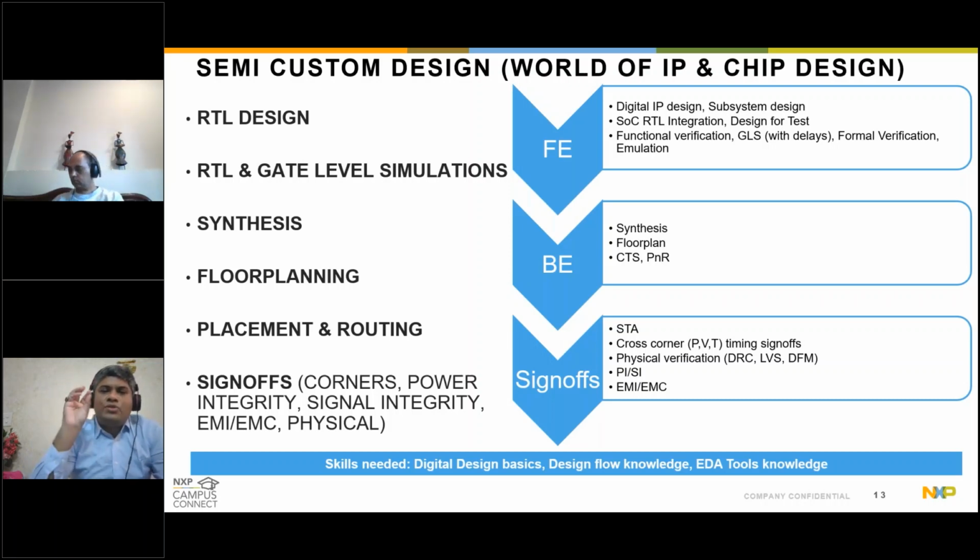But in this slide, we are talking about digital IPs, which means the reusable blocks or reusable design elements which get integrated into the larger chip. In the previous slide, those are full custom IPs. Those are also IPs in their own right, because they're intellectual properties for somebody who has created them. Here, we are talking about digital IPs, which means these are essentially in the domain of the RTL. These are soft IPs, right? These are not hard IPs. Previous ones are hard IPs.